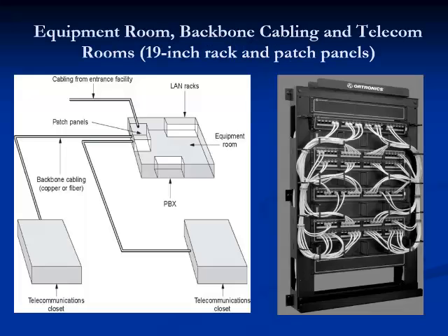This slide shows the equipment room and its subsystems defined by TIA 568. Equipment rooms are centralized spaces for building servers or campus-serving telecommunications equipment such as PBXs, computers, routers, switches, video and audio switches that serve the entire building or campus. The equipment room is a centralized space specified to house more sophisticated equipment than the entrance facility or the telecommunication room.